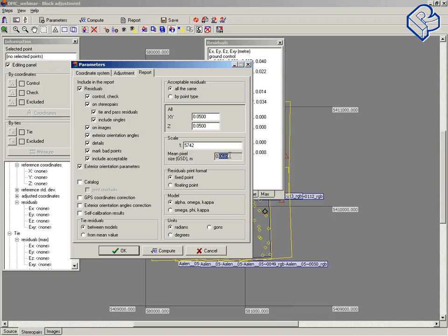You have to calculate the ground sample distance. If you want to reach the accuracy, you have to know that for any digital system, the accuracy of aerial triangulation is around the pixel. So, for example, now we have 7 centimeters on the ground, and we can expect that the block adjustment accuracy will be around this value. So you have to estimate what accuracy you actually need, depending on the output scale of your orthophoto plan or something like this, and make the aerial survey, taking it into account.